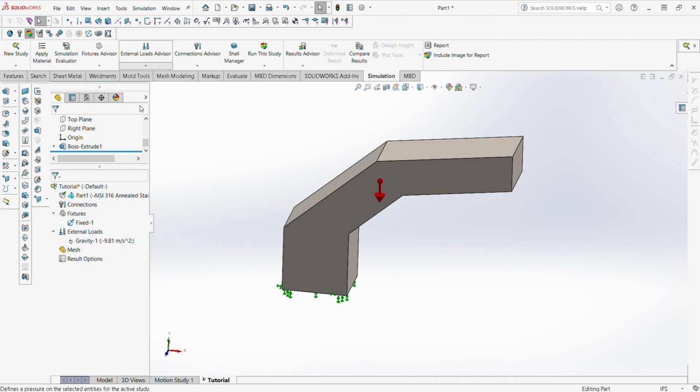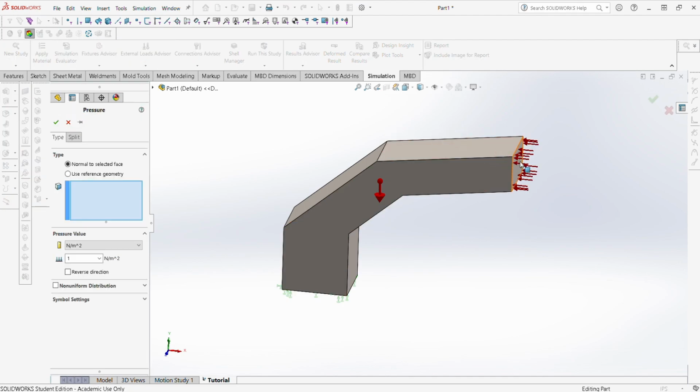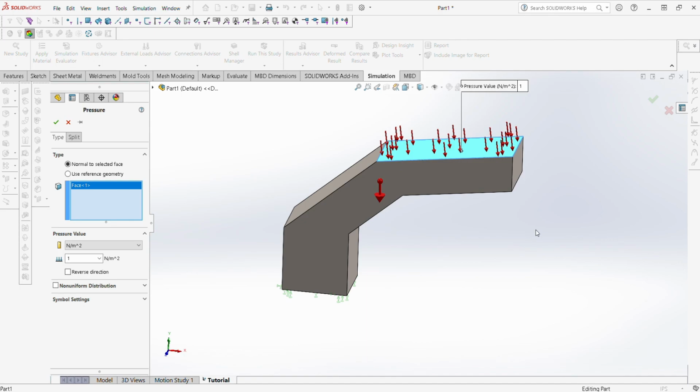And then I'm going to add a pressure here, kind of wherever you want, depending on how your part is being loaded. Let's say this is a step, for like a little step up, like you bolt it to the side of your tractor or whatever. That's the step. Since I'm American, we're going to throw PSI on there, pounds per square inch.